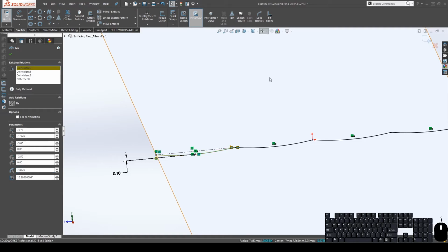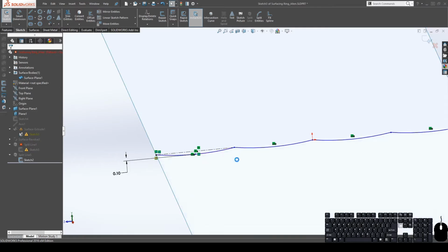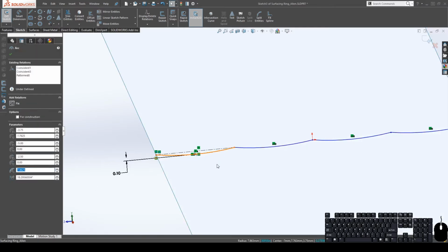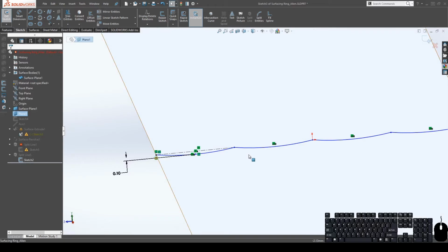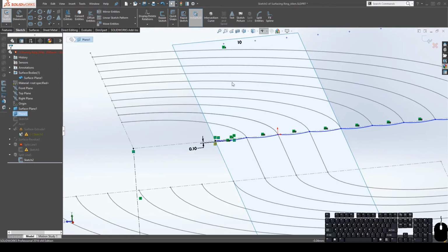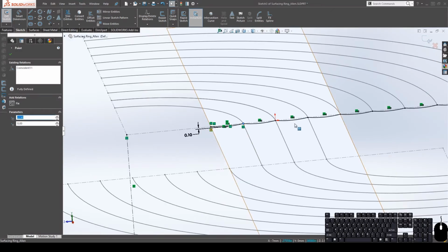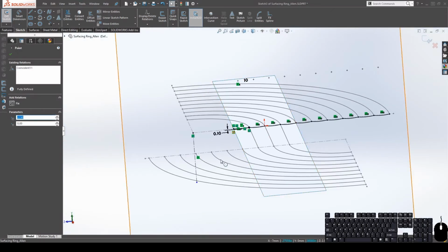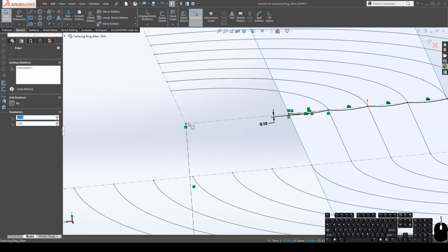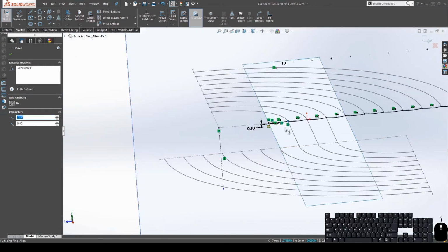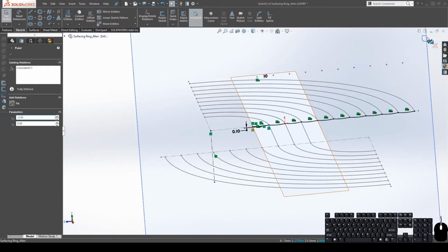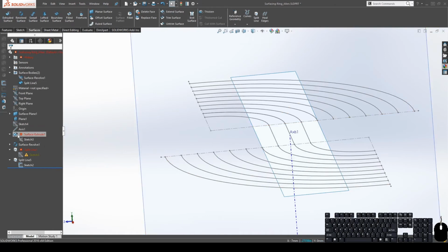View sketch relations on, we can go through here and just delete all of the kind of gross yellow relations. And then let's turn our sketches on so we can see here. We can fix that. So on your own, make sure you delete any relations that are causing an error and re-add them.